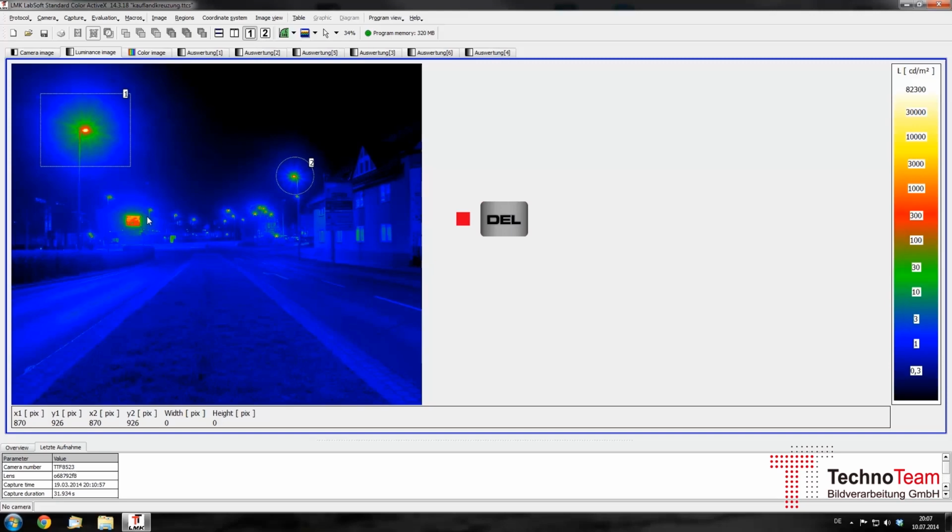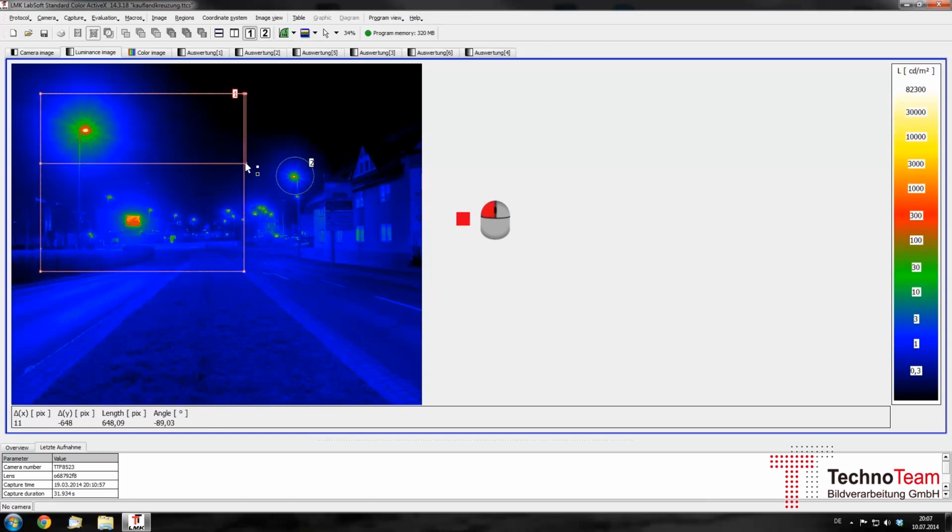on the keyboard. The contour points of a measuring region can be shifted, added, or deleted as required. If you take the cursor onto a contour point of a measuring region, you can simply click and drag it into a new position.